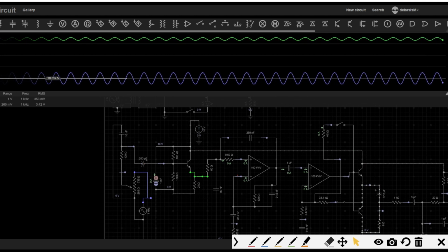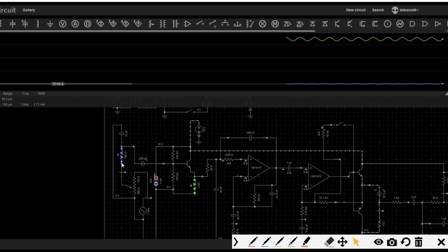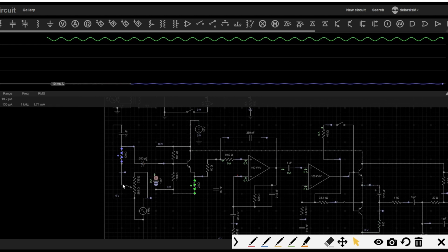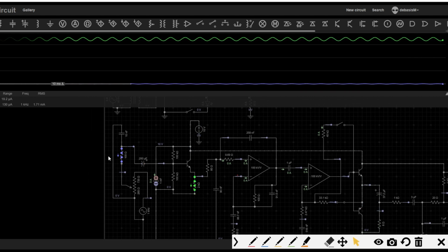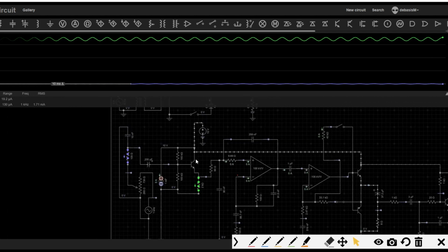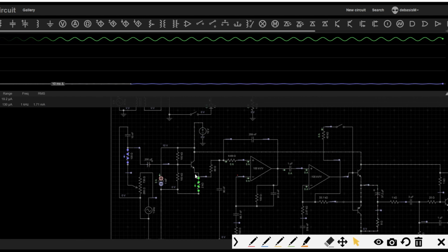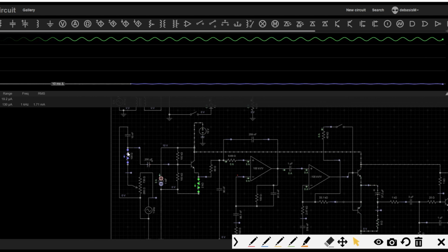Now if you see the current values, things will be a little bit clearer. You can see the order of current in this loop, meaning how much current is getting drawn from the audio pin, the audio source. It's negligible. You see, some microampere, 9.62 microampere of current is getting drawn. And see here how much current is flowing through this transistor, and the same thing is flowing through this resistor, the major portion. That amount is 1.77 milliamp, significantly higher than this 9 microamp.